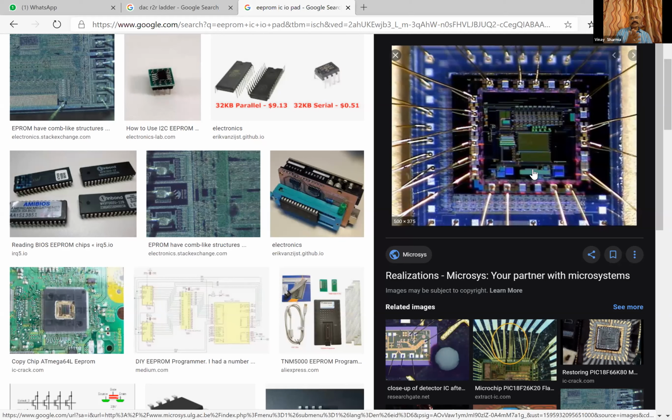Secondly, the IO pads generally are nothing but a simple layer of metal, okay, through which you just connect and solder a wire, and that can be any of your top metal layers. Generally, as the machine is going to come and impact it, what may happen due to impact is the metal can break or it can crack.